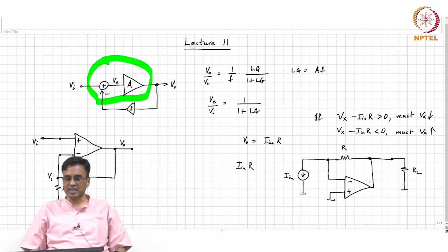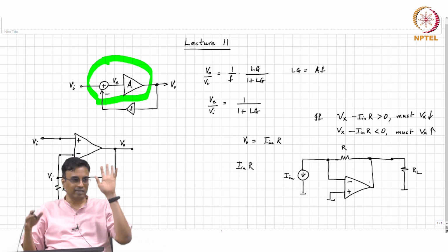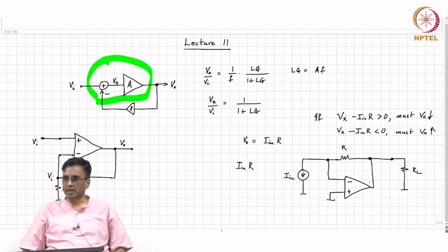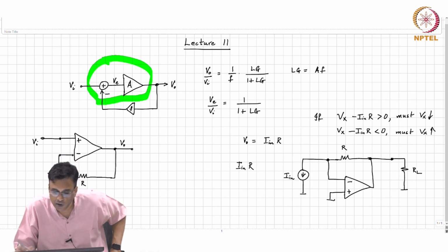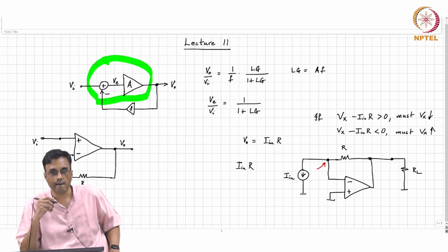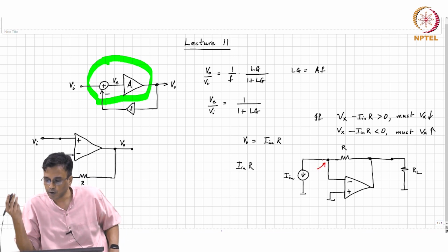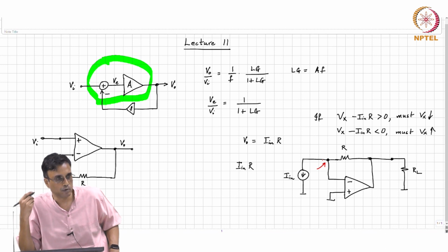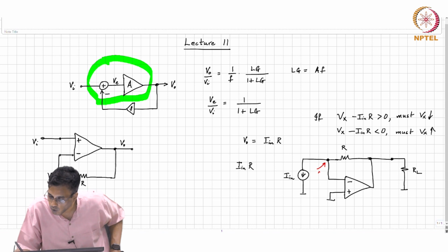So, as you can see, the signs on the op amp come out naturally without having to guess, copy from neighbor, open textbook, all that. All right. So, what is this voltage? Yeah, I know, but we know that that's an op amp whose gain is infinite. So, what comment can you make about that voltage? That voltage is 0.